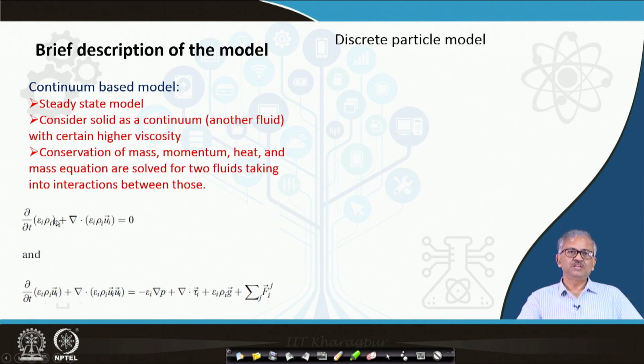This is basically the conservation of mass, the continuity equation, and there is the momentum equation, 3 components of momentum, as well as other equations like enthalpy balance and the species balance equation. And if you want to solve in turbulent K epsilon model, all will be there.